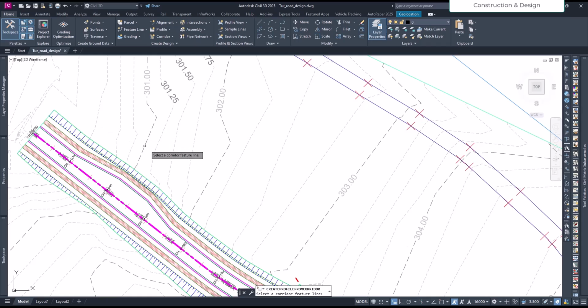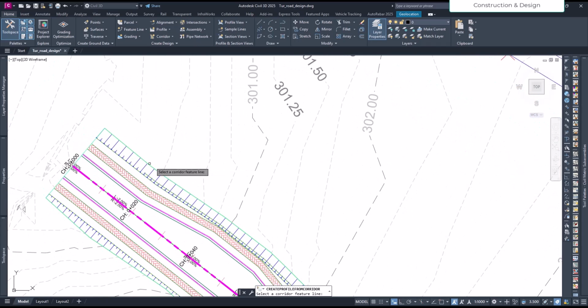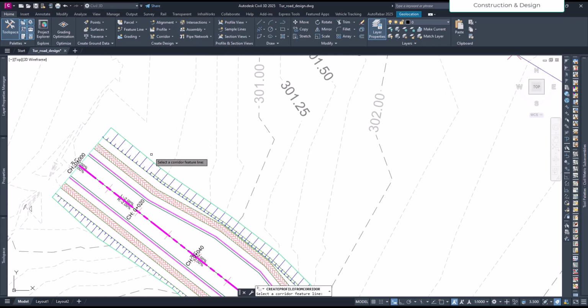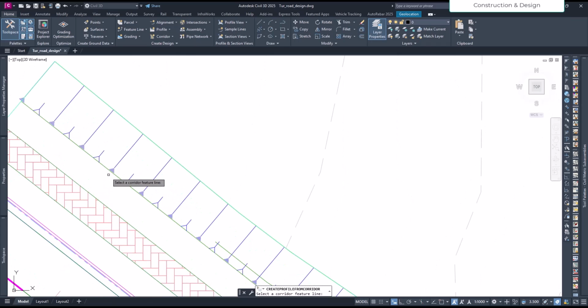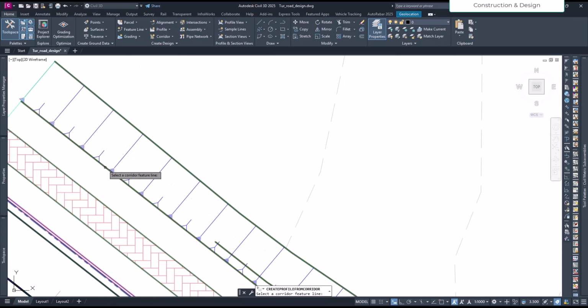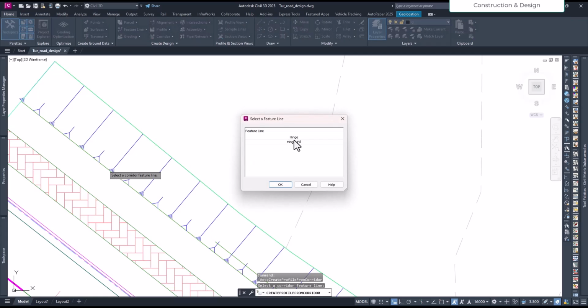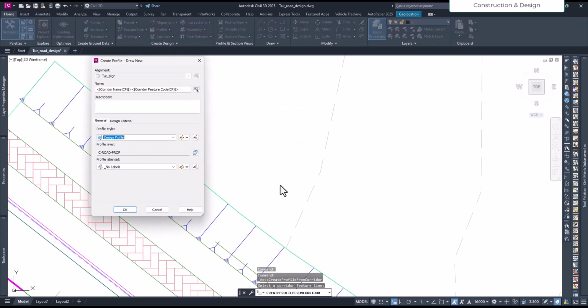To determine where we need those guardrails, we have to know the fill difference between the bottom toe and the top here. So first, I will take one of the lines, and it says hinge and hinge fill. I'll just take hinge and say okay. It's a design profile, just keep it like that. You can name it, maybe you call it edge.